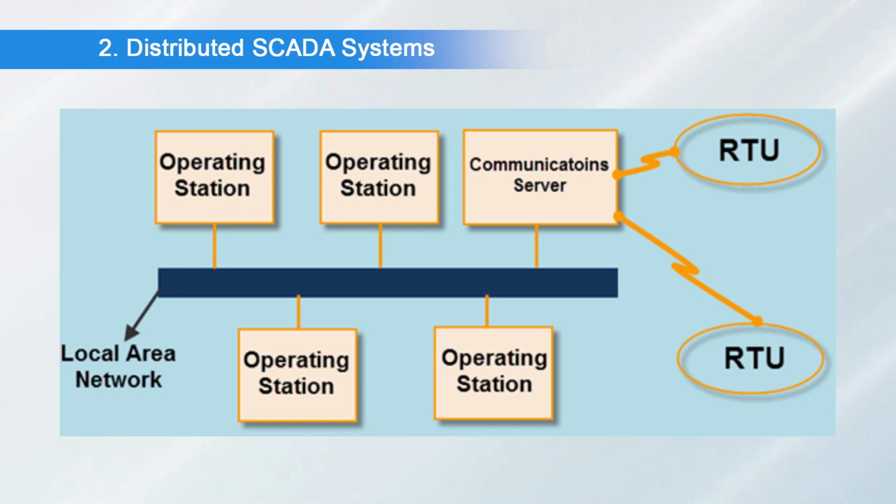As compared to the first system, where a single SCADA system was used and was not able to communicate with the other SCADA system, in this system multiple stations can communicate or can be linked with each other. You can refer to the figure. It is an extension of the previous version of the SCADA architecture. Here the single SCADA PC is now connected to a LAN, or local area network. On this network you can see the other SCADA systems are also connected.